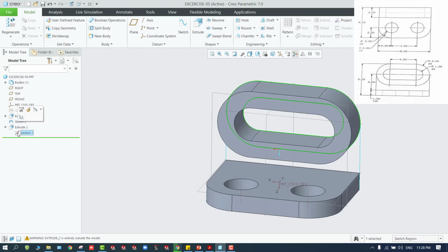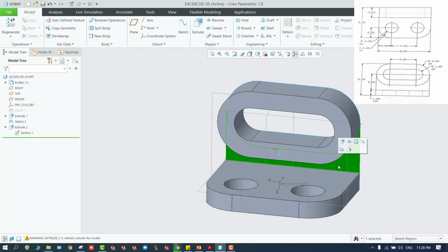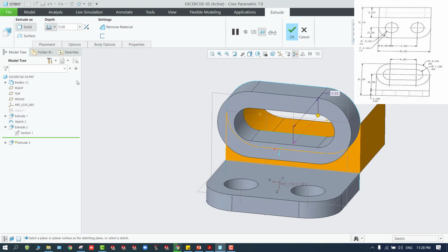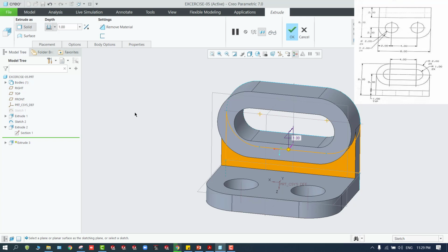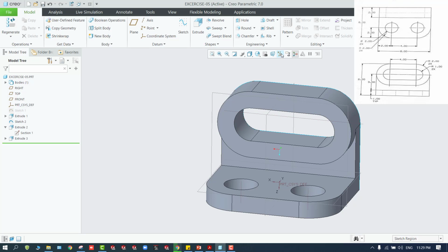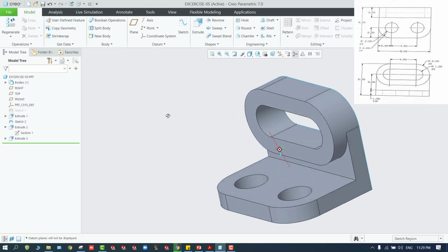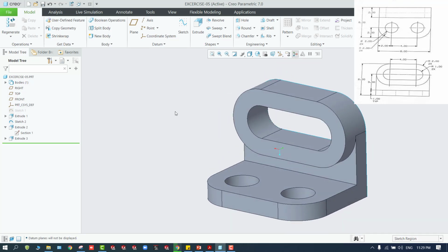Again, I'll go ahead with the sketch region is this, extrude reverse direction to 1 mm, I believe. Yes, so that is up to 1 mm. So you can simply click on OK. So you can turn off all the required edges and all. So this is how this sketch looks like. Okay, so that's all about this particular session. Thank you, stay tuned.